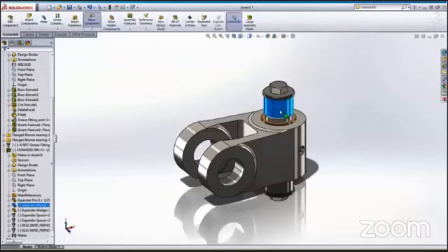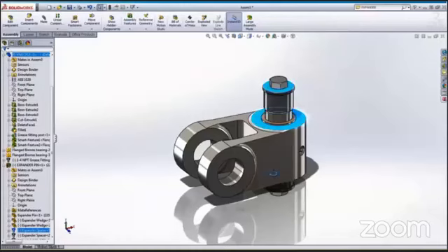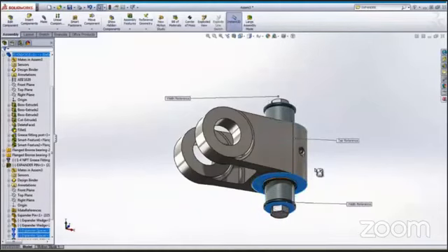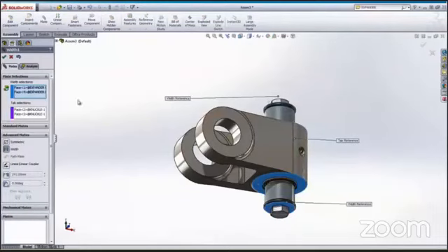So we could measure this pin and do some mates to position it with the distance mate, but a better way is to let SolidWorks do this with a mate. This advanced mate takes the selected faces and centers them to each other. It was easy and I didn't even have to get out my calculator.